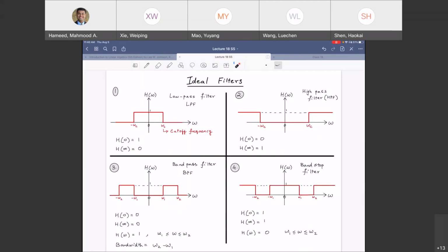If you had an infinite number of capacitors and inductors, would you be able to get it? Good. Right. So, here, what would be the impulse response of this ideal low pass filter? A sinc. A sinc goes on for how much time? Forever, right? So the impulse response of this is going on forever.